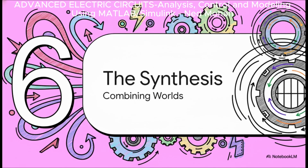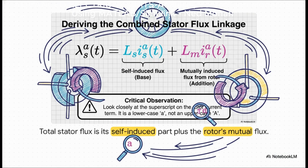Now for the most important step, the synthesis. We're going to combine these two worlds and see what happens in a real motor, where both the stator and the rotor currents are flowing at the same time. Okay, the crucial point is how we write this new equation for the stator flux. The first part, Ls times Is, that's the self-induced flux we already know. The second part, LM times Ir, that's the new piece. That's the flux that's mutually induced onto the stator by the rotor's current.